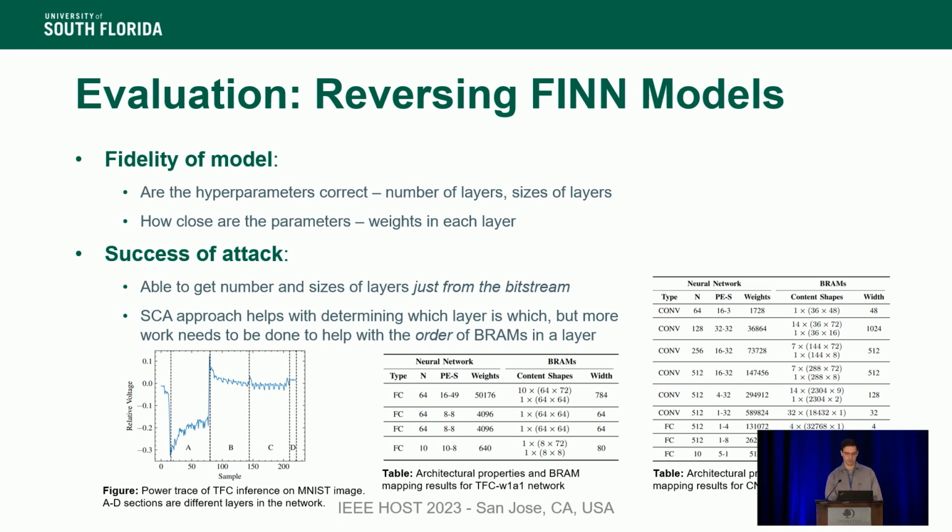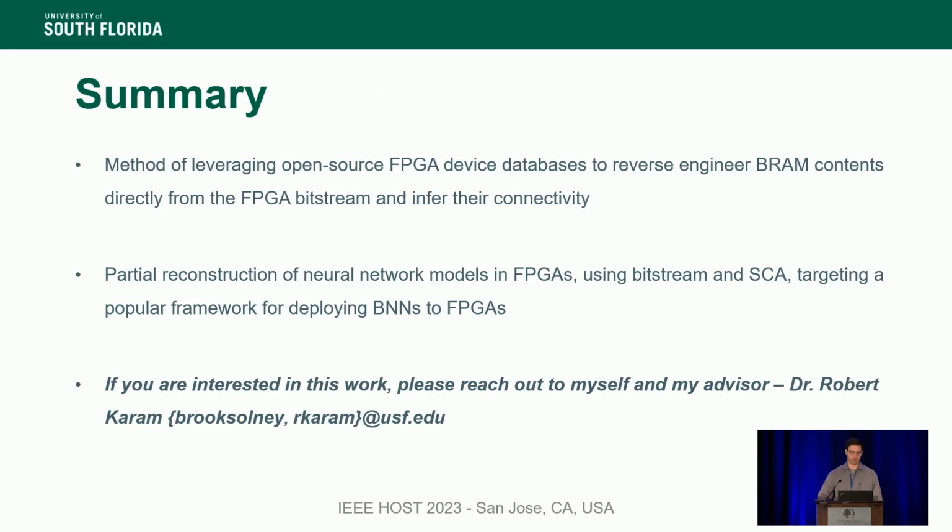So now I'll just quickly wrap up. In this work, we presented a method of leveraging open source FPGA device databases, Project X-Ray, to reverse engineer the BRAM contents directly from the bitstream and infer their connectivity. We achieved partial reconstruction of the neural network models in the FPGAs using bitstream and side channel analysis, and we targeted a popular framework for deploying BNNs to FPGAs.